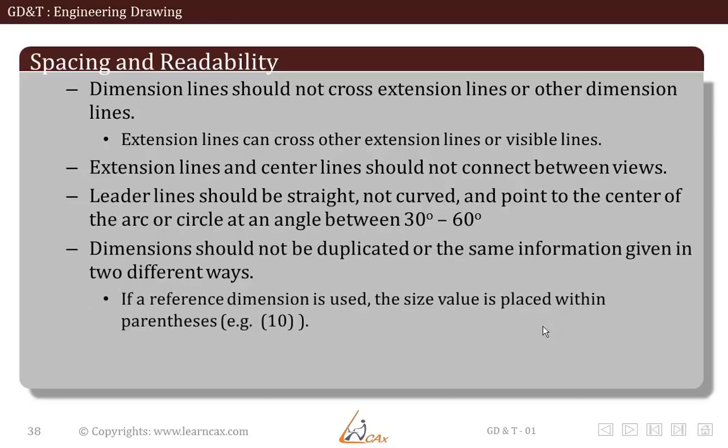Dimensions should not be duplicated or the same information given in two different ways. If a reference dimension is used, the size value is placed within parentheses. So make sure that two dimensions of the same feature are not present in your complete drawing.